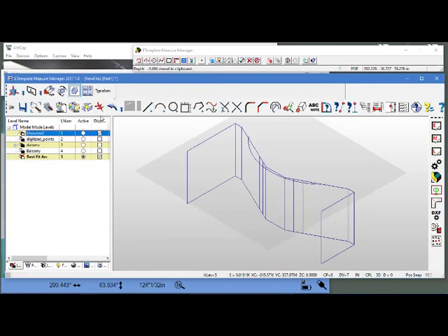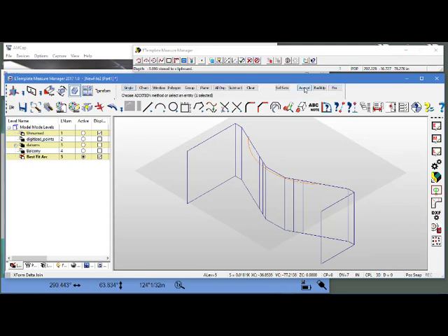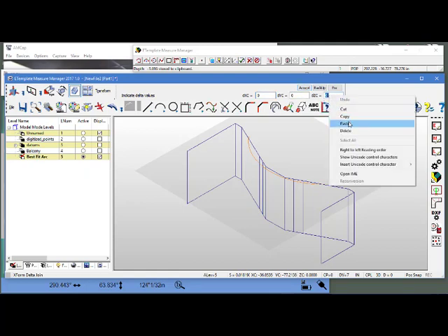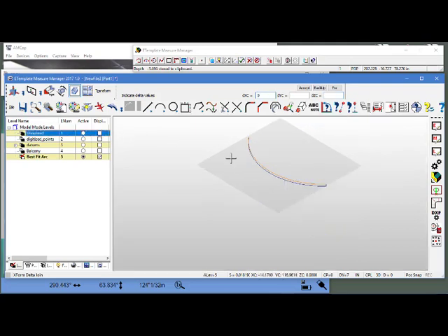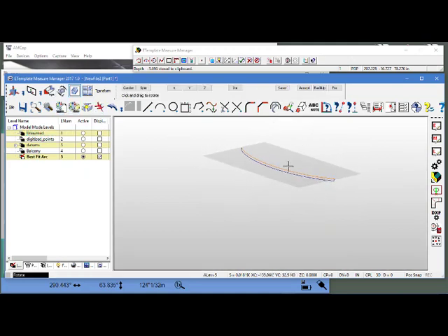It's going to ask me what I want. I'm going to say single. I want just this item. I'm going to accept just that item. I'm going to do one copy. No changes to X and Y again. And the Z depth is on our clipboard. I'll paste it in, hit the Enter key. And let me drop everything else off. And you can see that we've created a band where that balcony would be. And then we bring everything else in. You can see the full picture in 3D.